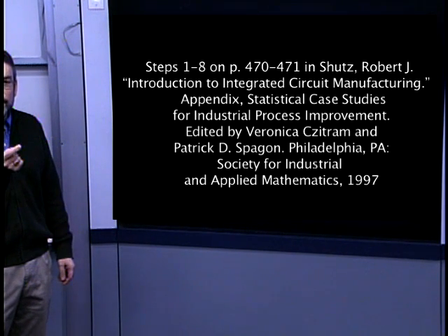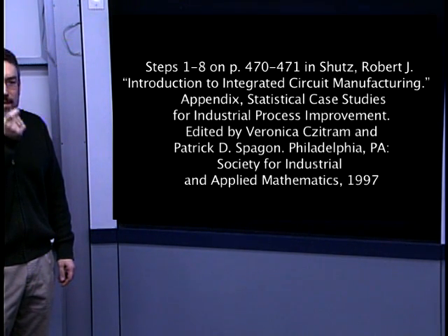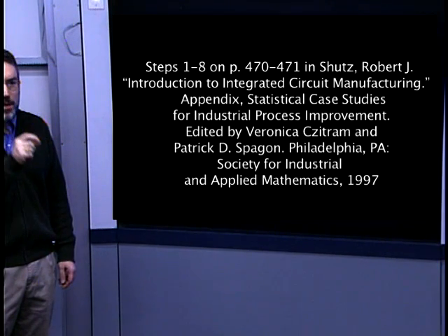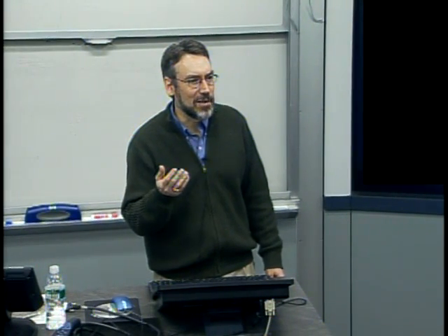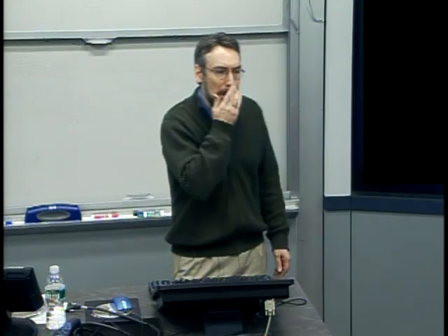Well, first off, to answer your question, you want that to be 100 angstroms plus or minus, well, in fact, some of the kinds of control that they quote are plus or minus 0.5 angstroms, which is less than an atomic layer in some cases, right?